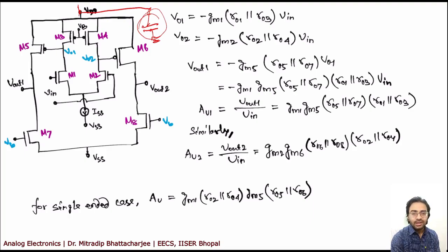However, for high frequency variations, or if there are different frequency components in the circuit, then you may not be able to nullify those variations like this. So you may need a lot of capacitors because this corresponds to only one frequency component, right? Or a band of frequency components. So this is not that straightforward if the variation is really serious, but this is one way you will find that people use.